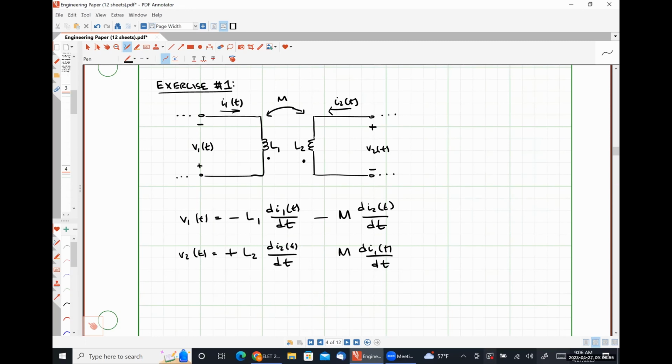All right. So for the mutually induced component, we already know that the positive polarity terminal is associated with the undotted terminal. So now we need to check, is I1 entering coil 1 at the undotted terminal? So that means we're going to have a plus sign here. Those are our voltages.